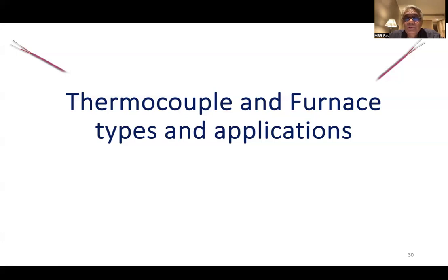Super kanthal, that is molybdenum disilicide rods, can be used to realize temperatures of the order of 1800 degrees centigrade. But of course, I also mentioned that molybdenum disilicide rods are very expensive, even for that matter, silicon carbide, because you're taking these alloys like nichrome or kanthal and semiconducting compounds like silicon carbide or molybdenum disilicide